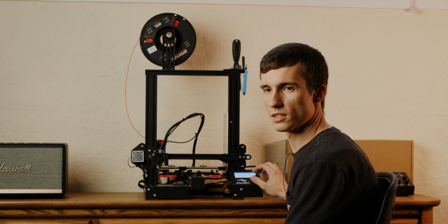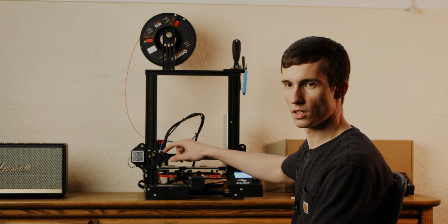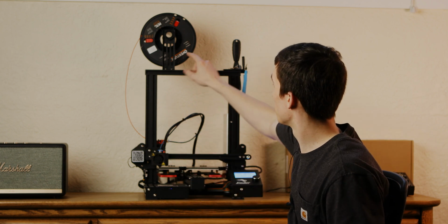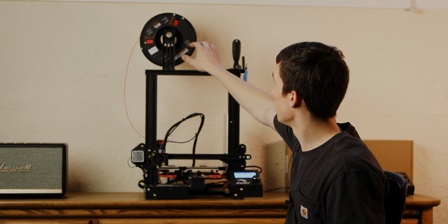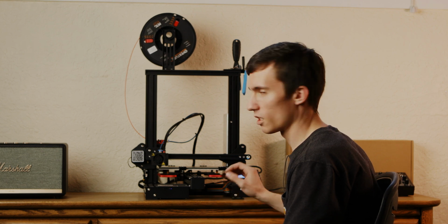I've already went ahead and set the temperature to 240 on the nozzle and 85 degrees on the bed, and that is like the proper parameters for the PETG material which I'm printing with. It's Overture PETG. I've done some experimentation, and that's the proper parameters you need for the print. So I'm going to get started with the bed leveling. You can just watch me do that.